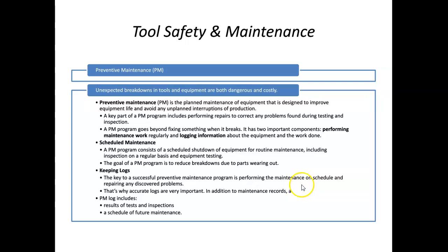So, and of course, keeping these logs is very important to make sure that we have those records and we capture those records. So that log should include different types of tests or inspections. Maybe for bearings, we're putting a thermal gun on it to see what the temperature is. Maybe we need to know how many times to pack it with grease if it's a type of bearing that needs grease, or gears that need grease so often. So we're going to keep those records and a log of that, as well as the log of any schedule of future maintenance as well.